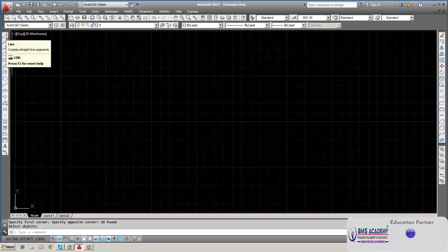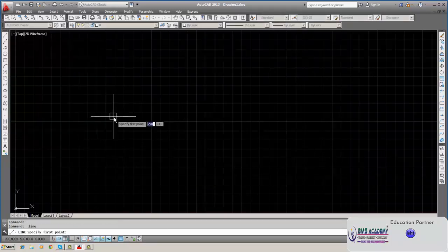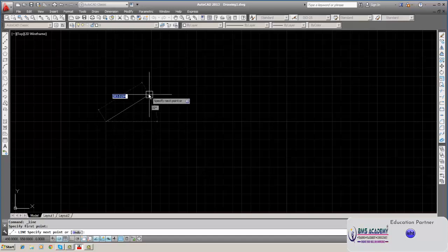Now suppose we want to draw a line here. Click here as usual. But here it picks up wrong points. See, you can't have any fraction point. We have set it in multiples of 10. You can pick up 250, or you can pick up 290, 340, like that in tens. Suppose I pick up 250. Click here, and if you want to draw a fractional line, not in multiples of 10, then you have to enter the values here and the angle also.